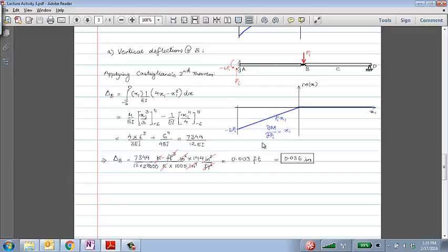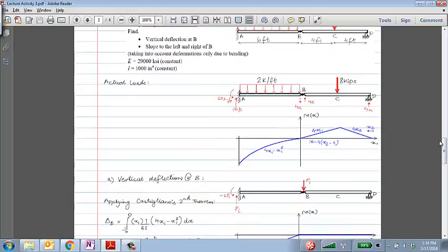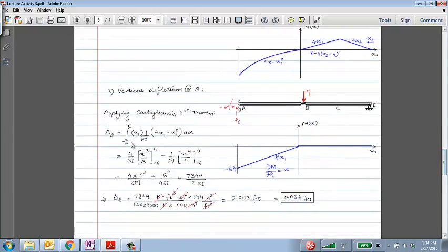So the derivative of the bending moment diagram due to the additional load with respect to Pi, not with respect to x, gives you just x1. So that x1 goes here, derivative times curvature, right? Additional derivative times real or actual curvature is what we need. This actual curvature was 41x squared minus x1 squared. This is basically just the equation of this bending moment diagram.